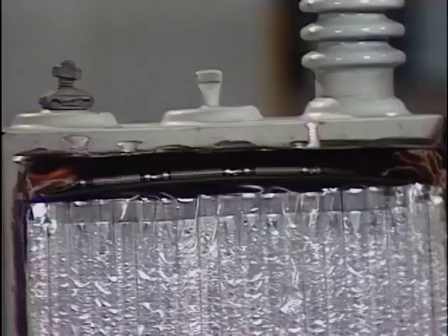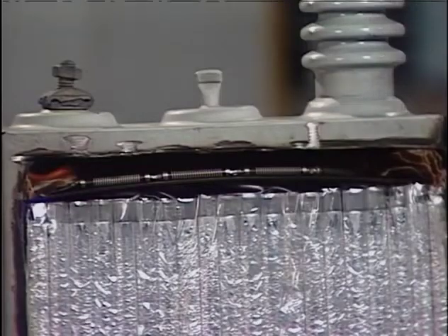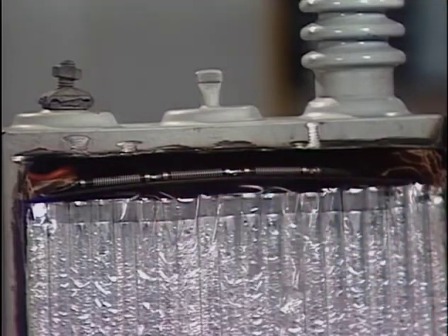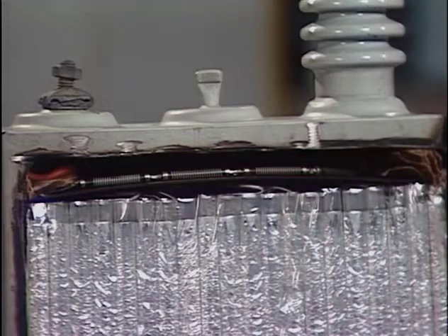Substation capacitors, like this one, can store thousands of volts. Does this mean that when you ground a capacitor bank, you're going to have a violent discharge of energy? The answer is no, and here's why. Substation capacitors are typically built with internal discharge resistors, like this. When the capacitor is separated from its source of energy, the resistor bleeds off residual voltage. Generally, the resistor is supposed to bleed the charge down to 50 volts or less within 5 minutes. The 5 minutes is important.